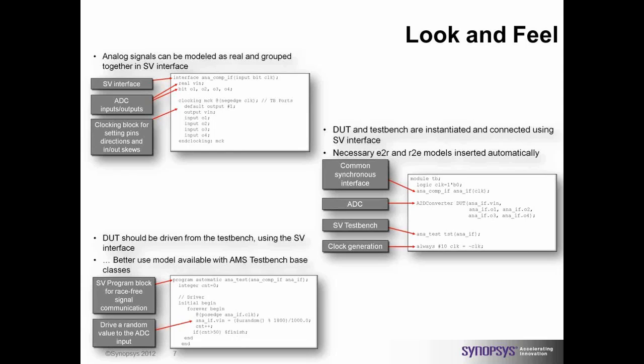And then finally, towards the left-hand side, you can see that the program block or the driver instance, which is trying to drive that particular real signal inside the interface, is actually able to drive a particular voltage on that real variable, and that real variable will pass it down as an electrical value to the actual SPICE DUT. So the bottom line is we now have something available to drive and sample SPICE DUTs from SystemVerilog.